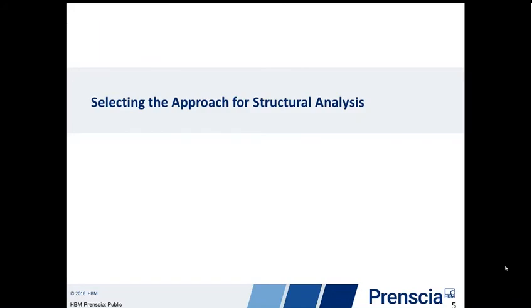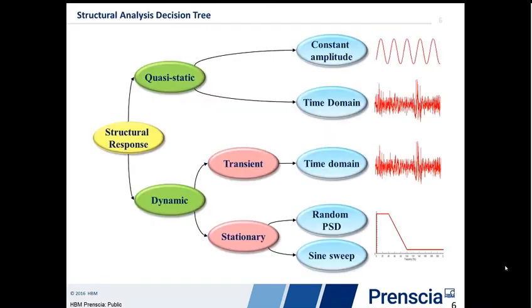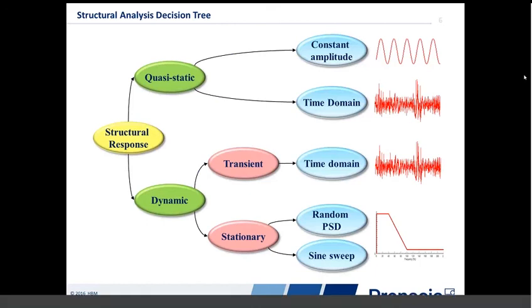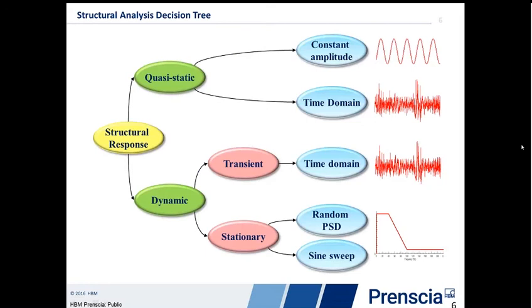First, just lay the groundwork. When we're doing structural analysis as the front end of fatigue analysis, we actually have a large number of options. We can work generating FE results, linear static. We could have either constant amplitude or maybe fluctuating stresses as inputs to a quasi-static analysis.